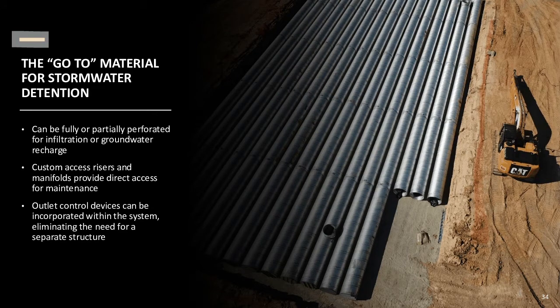Another advantage of corrugated steel pipe in these kinds of applications is that it can be fully perforated for applications where you want to use some of the available volume in stone storage around the system. That can be used, and also for recharge systems where the local geology will allow you to recharge some of the site soils in those areas. You can do full perforations or partial perforations easily and economically with corrugated steel pipe systems.